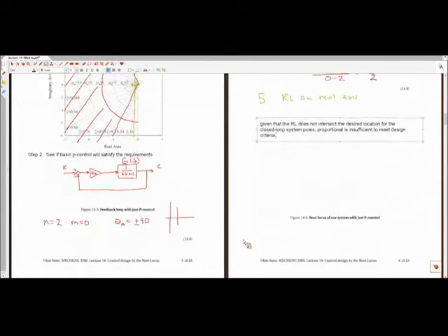All right, so then we have to do something about that, right? Okay, so what we're going to do is we're going to be modifying. We have additional gains that we can play with here, or additional terms that we can play with here, we're going to actually force the root locus to go through a location that we want it to go through. And so then the first thing I want to point out in terms of how we can make this root locus plot change